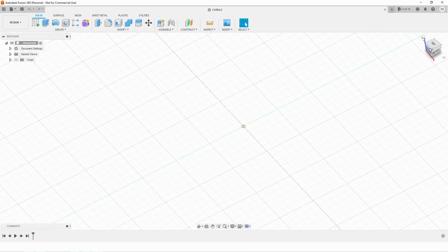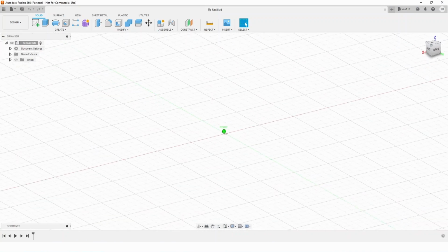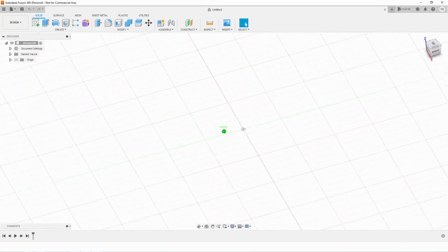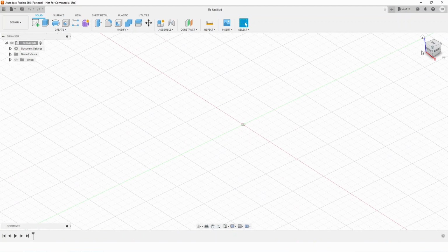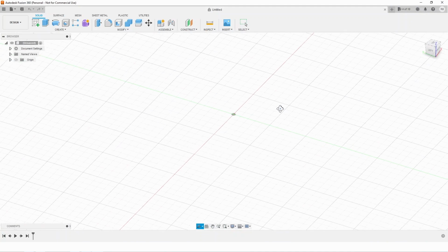Well, we can press our left mouse button and drag around this view cube to orbit, like so. Or we can press the top text right here. We can easily go to the top orthographic view. And by orthographic, I mean there's no perspective in that view. So if we want to rotate out of this, we just rotate our camera and we get our perspective back.